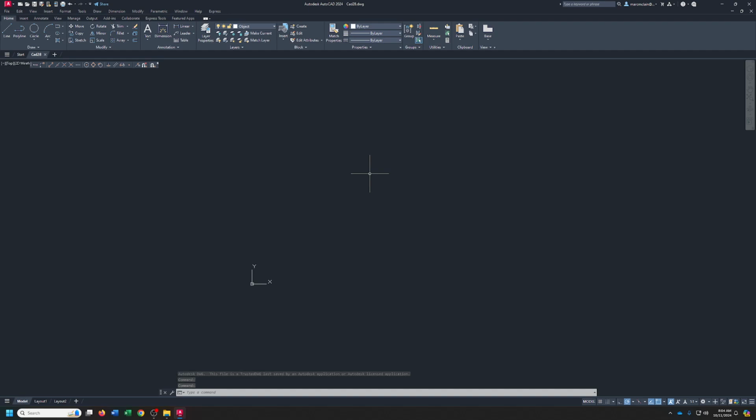Now in the previous one, I set up all kinds of construction lines and everything like that, and you can do that if you want to, but now I'm going to show you another way, the way that I normally do it. So we look at our part in the book and we see some dimensions on a three-dimensional part. What I want you to do is go from that bottom left corner and look at that face and you'll see 3 dimensions. Actually, you'll see more than 3, but the 2 that are most important are the vertical one, which is going to be 1.75, and then the horizontal one, which is 3.25.